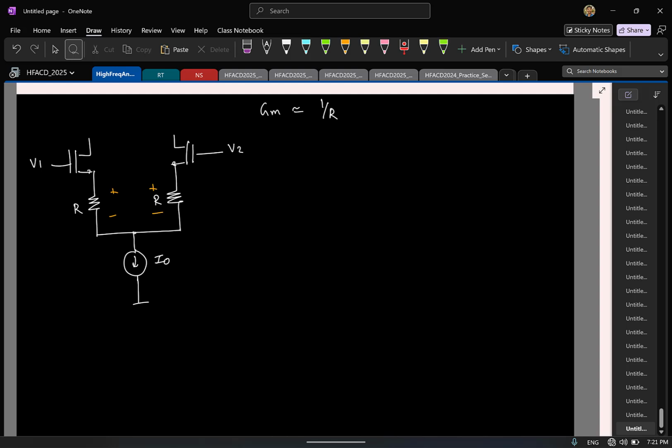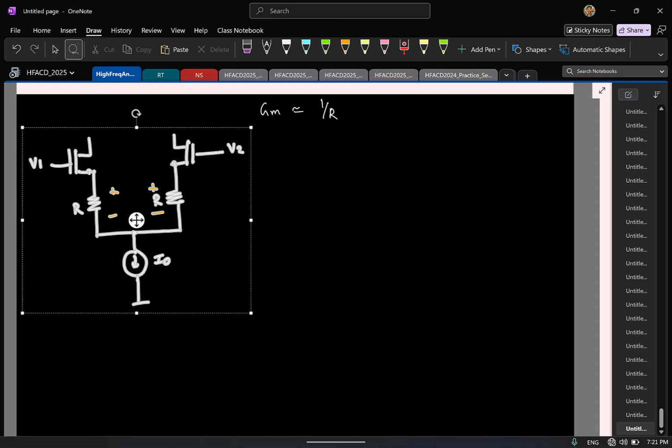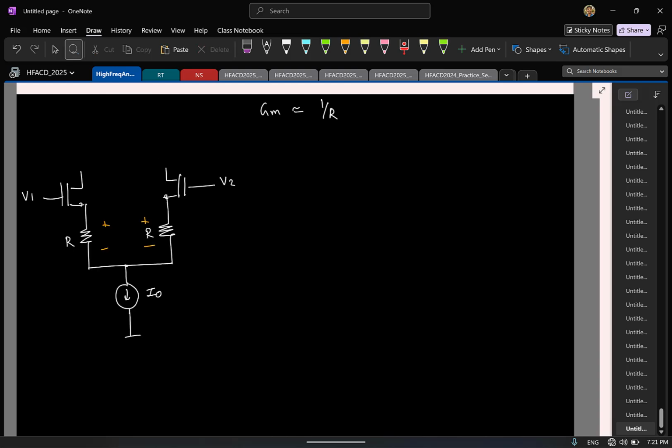For that, tell me if you want the resistor to be present for the DC picture or only for the AC picture. Only for small signals which you want to amplify, you want the resistor to be present. You don't want the resistor to be present for the DC operating point picture. So with respect to the operating point, I don't want to connect the resistor here directly. I don't want the resistor to be providing a DC path. The resistor should be connected from the source to a small signal ground for small signal behavior. So how can I connect the resistor to the source now?